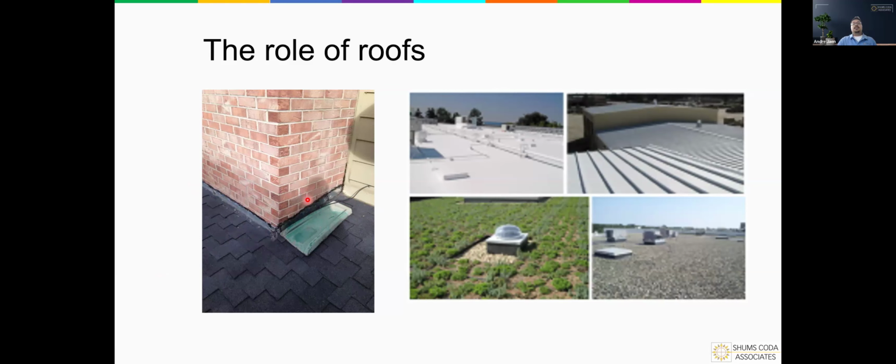to think about all the places where we're abutting either the thermal envelope or unique bits of dissimilar materials in our construction, where we have masonry and then we have what looks like wood siding over here based on this picture. But it's a good example of remembering that we still have to have continuity of the thermal envelope. We have to plan for these spaces effectively. And then, of course, we have to make sure that the roofing materials themselves are installed properly.